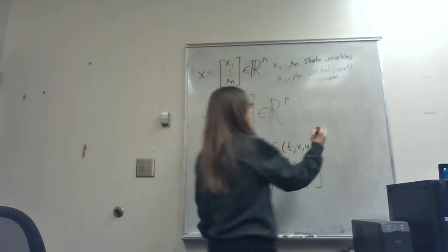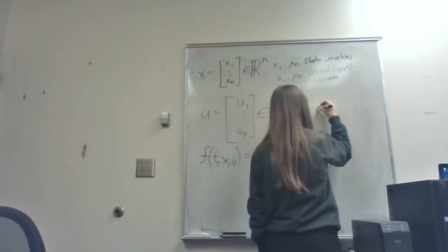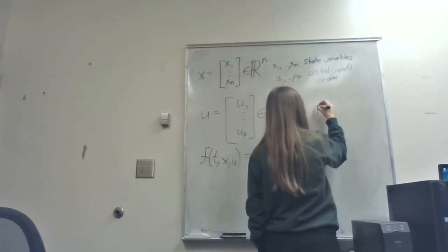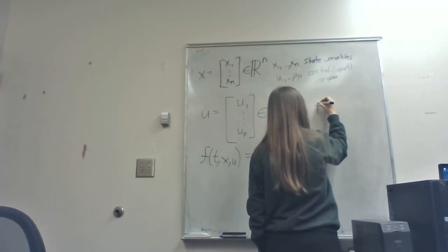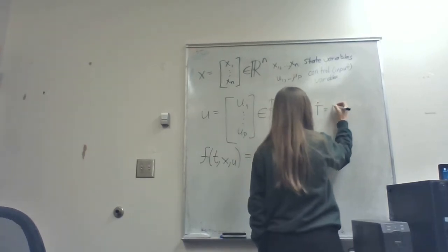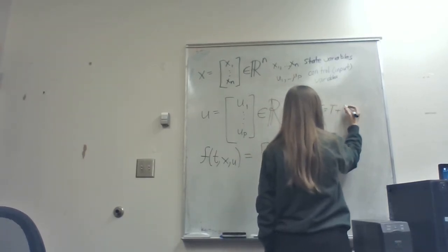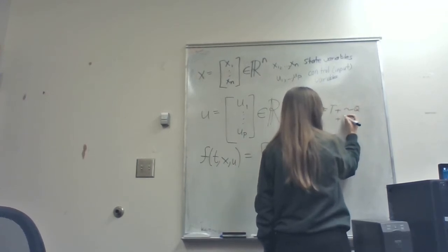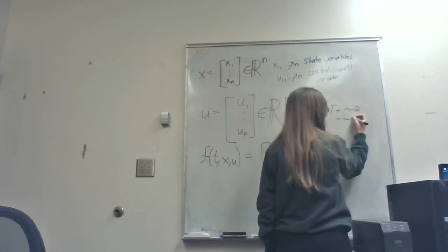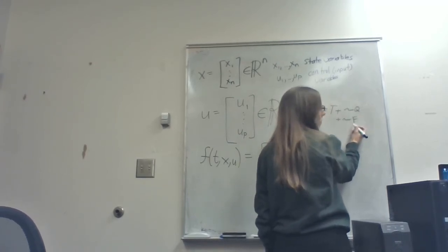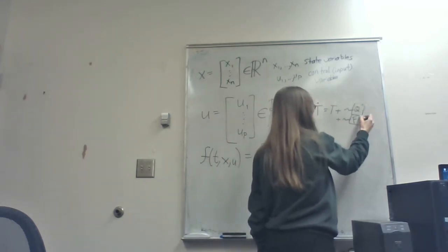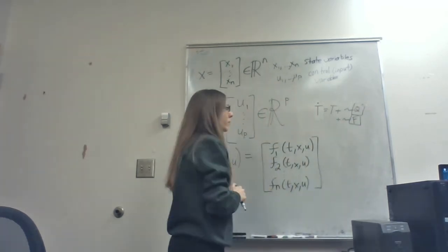But in theory you could write a differential equation where, say, temperature dot is equal to the temperature plus something related to the heat plus something related to the enthalpy with the inlet flow rate, and say that both Q and flow rate here are changing.